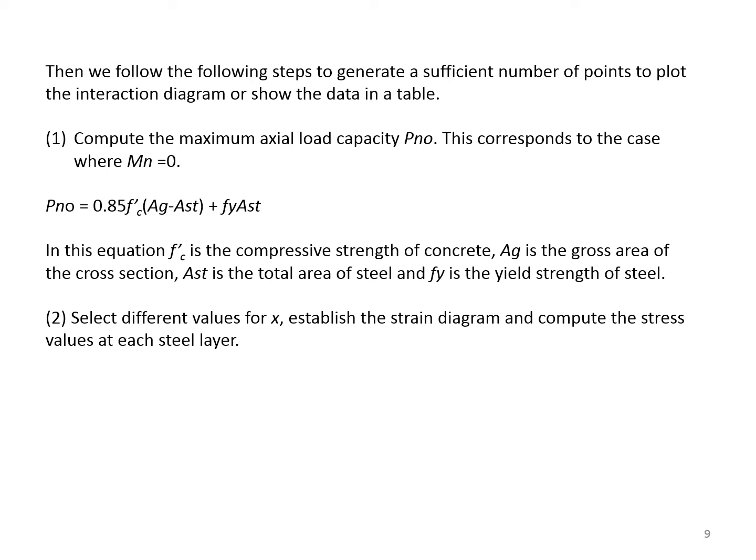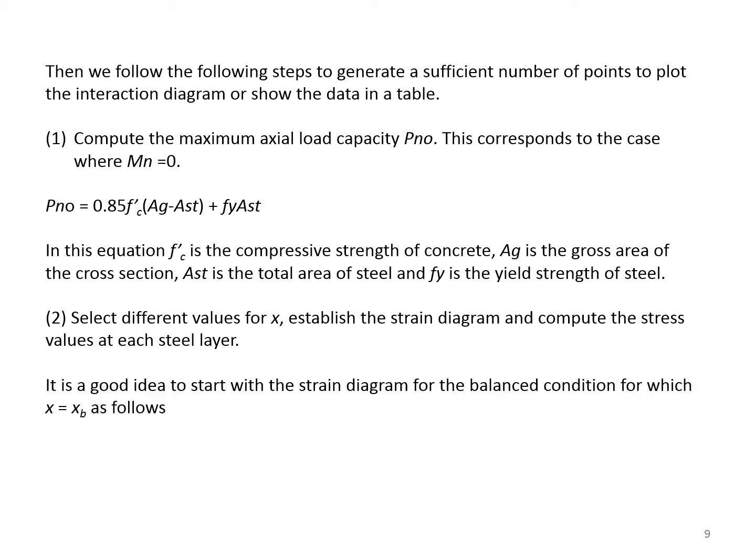Step 2. Select different values for x, establish the strain diagram, and compute the stress values at each steel layer. It is a good idea to start with the strain diagram for the balance condition for which x is equal to xb as follows.